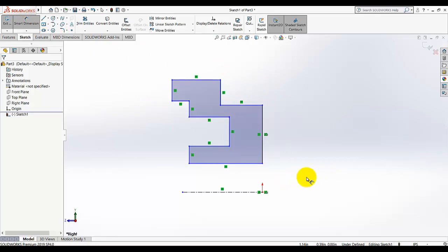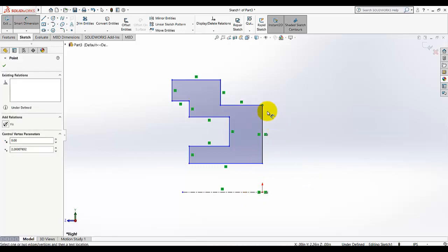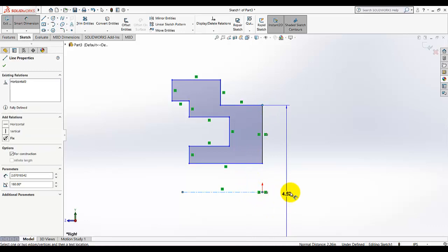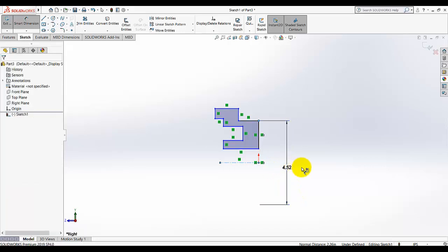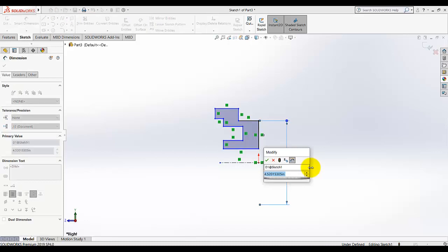So as you know, I am going to do it by adding some diametral dimension. For this point and this reference line, I am going to draw a diametral dimension. So I select this point and this line. Here you see a half dimension, and if you move a little bit lower than this reference line, it will show a diametral dimension. This is radial, this is diametral. So just add the diametral dimension. This dimension is given as 6.12.